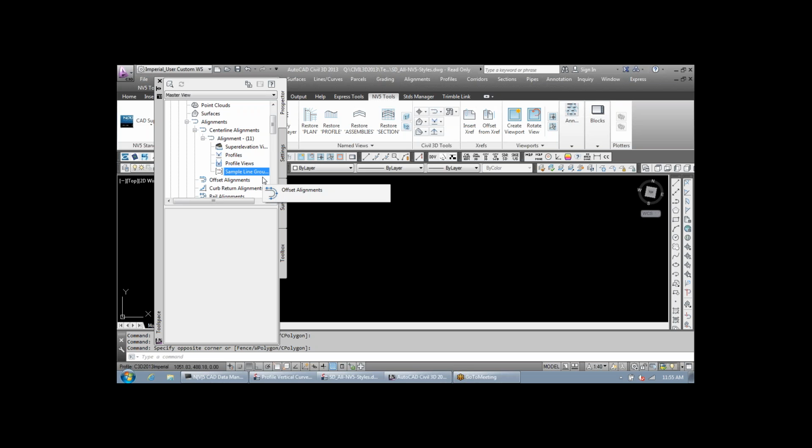In your section view, you can have it basically be part of your grid. So it'll show up on a layer. You can set the style to be, right away, blue and Phantom 2 or whatever you want. And it'll show up in all your section views. So rather than having to calculate, oh, that's 10 feet offset or 10.53 feet offset from my center line of my section, and then drawing that line, you can have it automatically do it just by setting your right-of-way as an alignment.